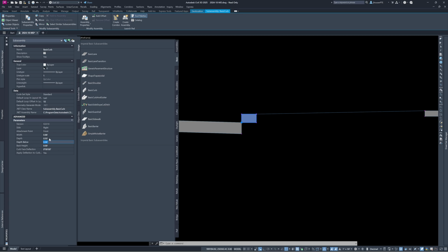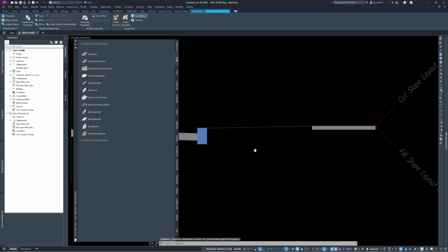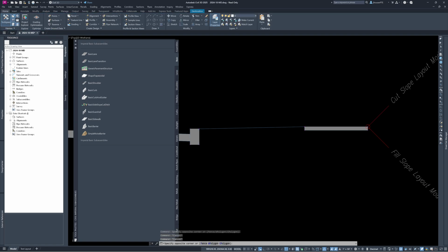So if we really want to get really particular in the future, we could create our lanes with the curb actually sitting on top of it and go through that. For the most part, we haven't gotten that detailed. There is no real good reason to do that at this point, but it is possible. So if you have someplace that you need to do that, it's definitely something that, detail wise, we can really get into the nitty gritty of all the details and depths and widths and make it completely accurate for takeoff quantity purposes. All right, so that's the 6-inch curb with the proper width.